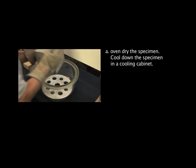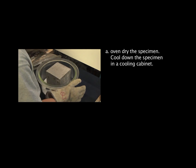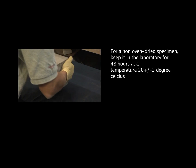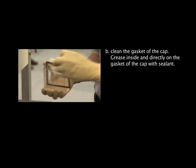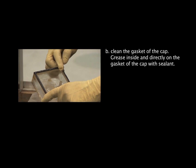A. Oven dry the specimen. Cool down the specimen in a cooling cabinet. For a non-oven dried specimen, keep it in the laboratory for 48 hours at a temperature of 20 plus or minus 2 degrees Celsius. B. Clean the gasket of the cap. Grease inside and directly on the gasket of the cap with sealant.